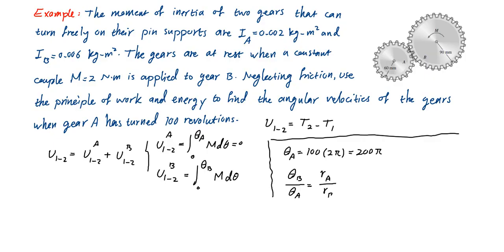So there is an inverse relationship, right? And you can guess that. For one rotation of theta B, theta A rotates more, because it's smaller. It's pretty intuitive. And you have to go with RA over RB. This is a solid relationship. It is always valid: the rotation of this gear over the rotation of this gear is equal to the radius of this gear over the radius of this one, when you have two gears engaged.